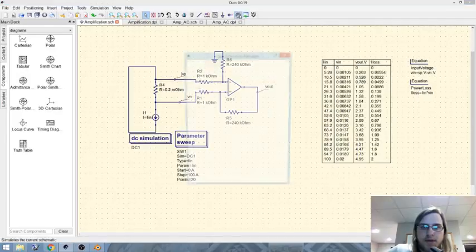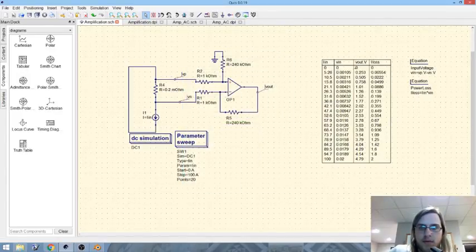And then we're going to rerun the simulation. And so right here you can see the details of my simulation: I'm doing a parameter sweep. So I'm going from 0 amps from this current source all the way to 100 amps. And then my output, I'm looking at Vn, which is the differential voltage across this resistor. So this voltage minus this voltage. And I'm getting that through this equation right here, Vp, which is marked right here, minus Vn, marked right there.